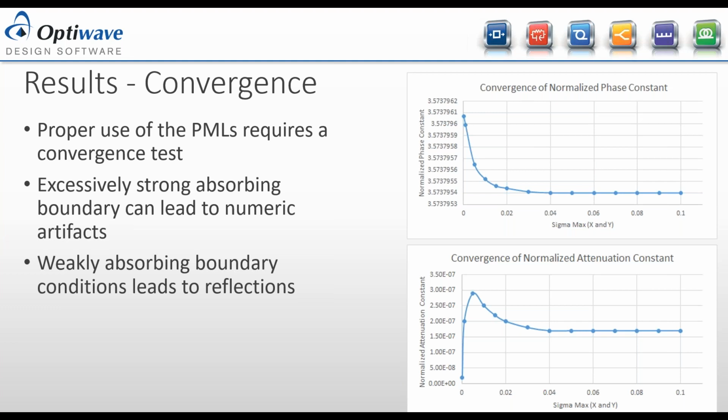It's just saying that if you excite a waveguide, say at z equals 0, maybe with a very bad excitation, like a not clean source, a point source that's just going to vibrate the field in any direction, then if you look really far away, at z approximating infinity, the field you're going to see, if the waveguide has a fundamental mode, is going to be the fundamental mode, and that wave will be propagating with that associated propagation constant.